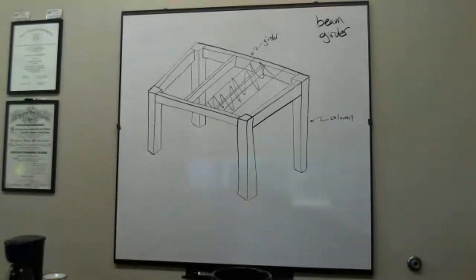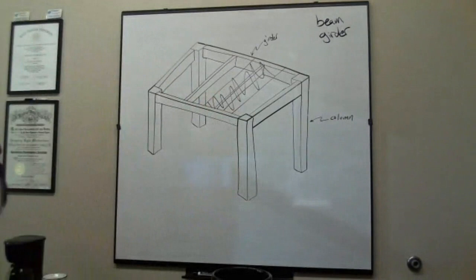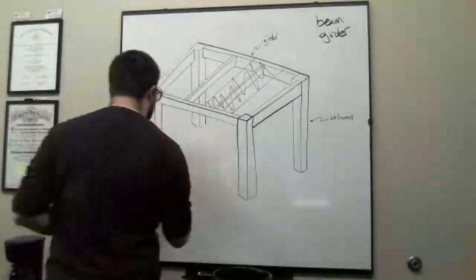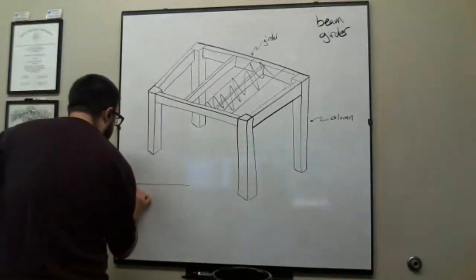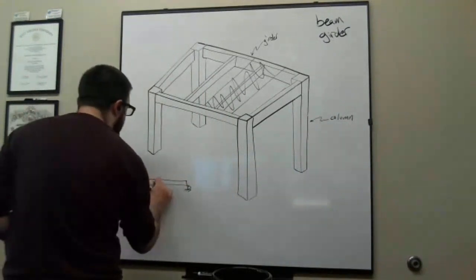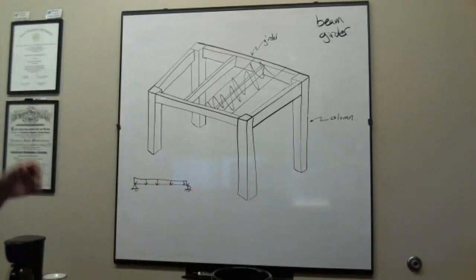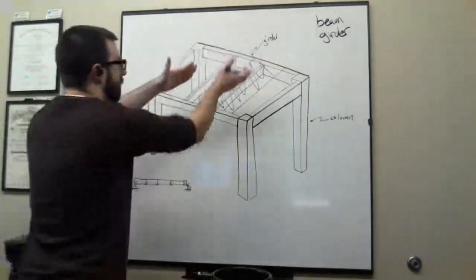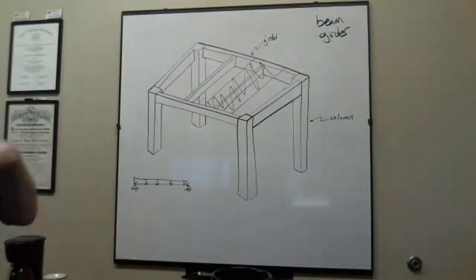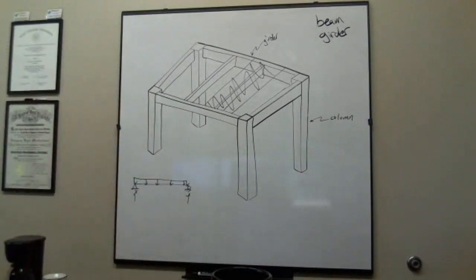Now, the way that we're going to handle this is we're going to say, okay, I've got a beam that's experiencing a pressure load of, I don't know, 50 pounds per square foot. Take that pressure load, multiply it by this tributary width, and I have a beam, and we'll say that's simply supported, that's experiencing a distributed load. And so that's how I would model that floor beam, okay? And so, here's the length of the beam. I've got this pressure load multiplied by width to get a distributed load. And so I can take this beam and I can determine support reactions. I can draw a shear diagram, draw a moment diagram, what have you.